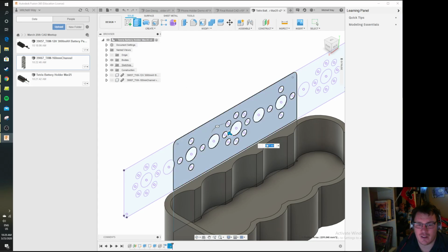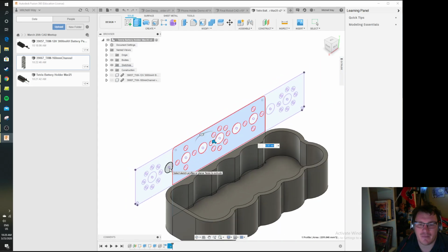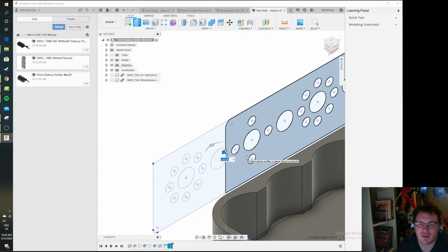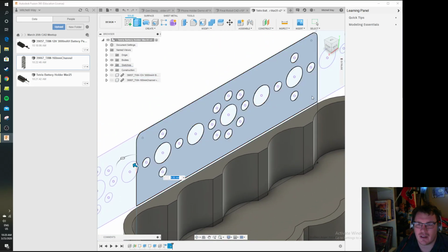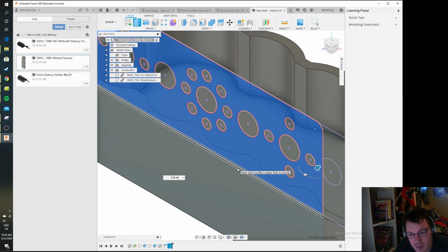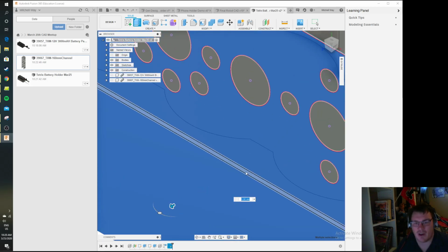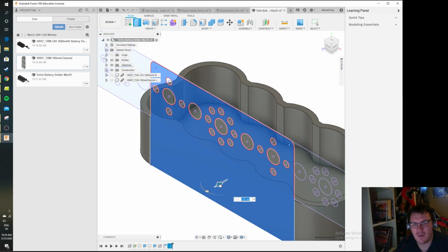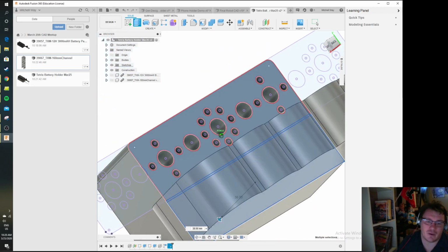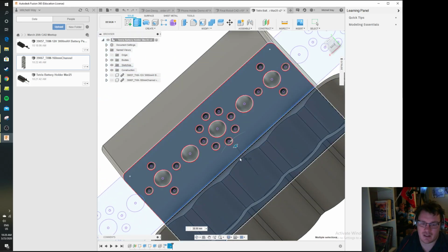And I'm going to click this part of the actual sketch. I'm also going to click on a couple of other little pieces here just so I make sure that I get all of it in. That also shows me that it wasn't quite centered. Apologies for that. And now, most importantly, I'm going to click on this bottom piece here. The little gap between them and the bottom piece. Everything in blue now will extrude out if I wanted to create a part, which is exactly what we're doing right here. And in this case, I'm going to make the part.